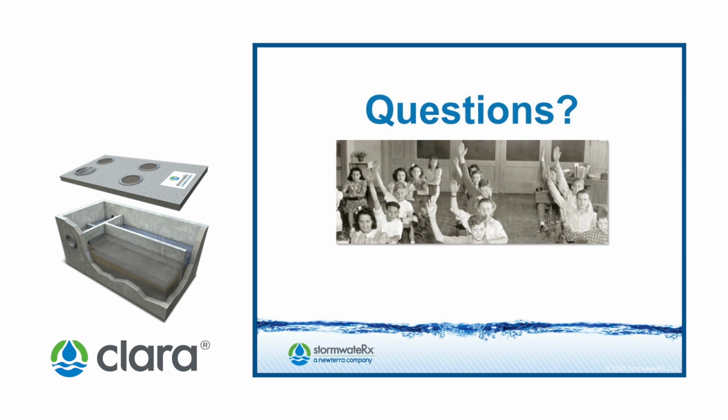It's sort of a balance. We don't want it to be too much because the way to generate that additional head is by surcharging the water upstream. So we want to make sure that we're preventing excess flooding of upstream infrastructure.